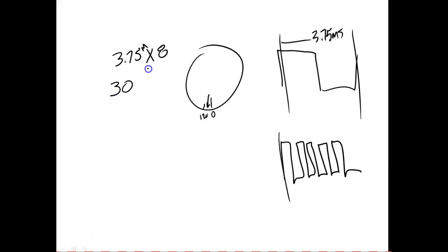It comes up, it gives me what? 30 milliseconds per revolution. Okay. Now what I've got to do is get my time over to a frequency, right? You understand? So we've got two options. I could multiply this by 60, or we'll take the reciprocal of that, and that turns time into what we call a frequency, right?